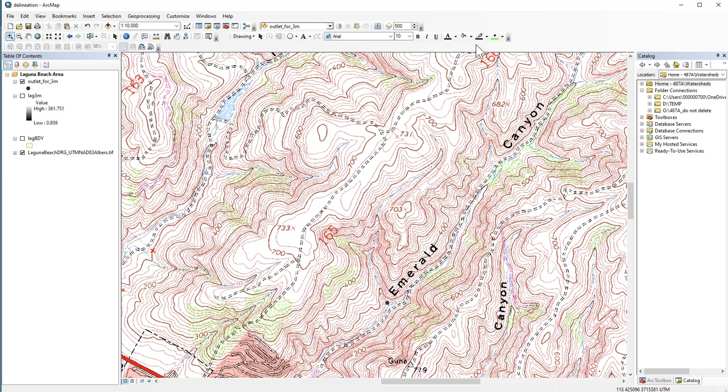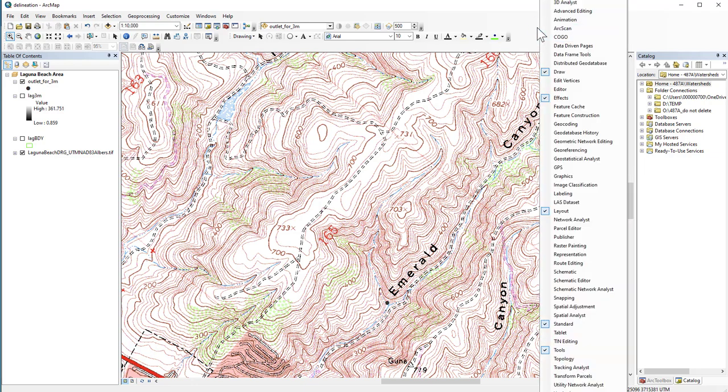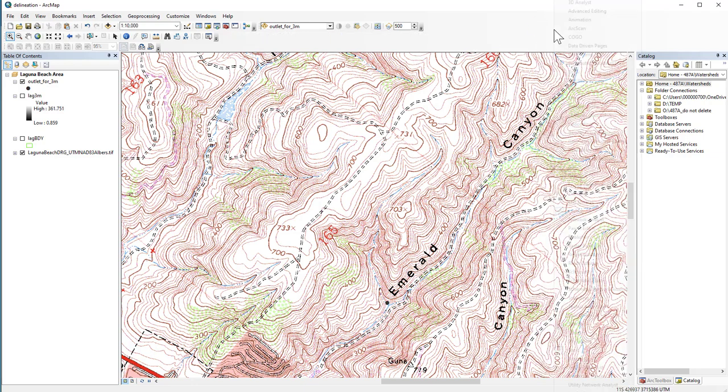So we're going to go to our drawing tools. If you haven't activated them, if you right click on your menu bar and select the draw tools, they pop up. And we're going to select the polygon tool. And if you did this by hand, I had you connect the dots or draw dots that indicated that watershed divide. Here we don't have that luxury, and we're just going to have to use the polygon itself to identify those vertices, which is when every time you click your mouse, you create a vertex.